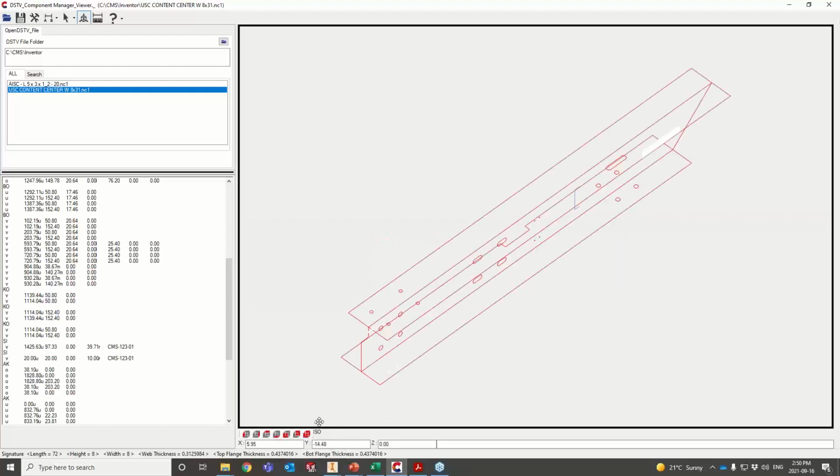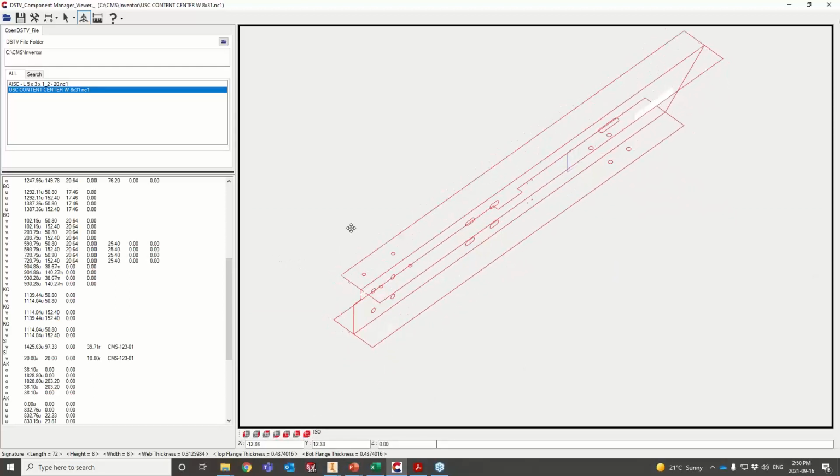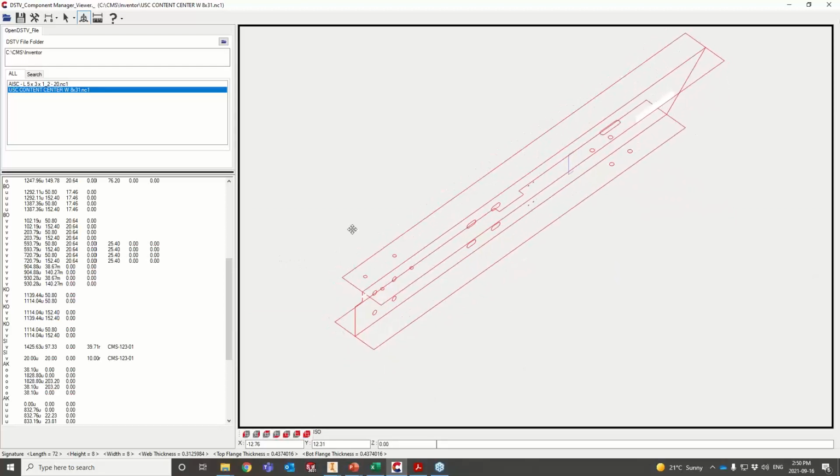So this tool can be used to verify your Nc1 file visually, right? So what the process would be, you create your Nc1 file. Once you're done creating your Nc1 file, you come to that viewer, open your Nc1 files, and visually do the quick quality assurance, right?